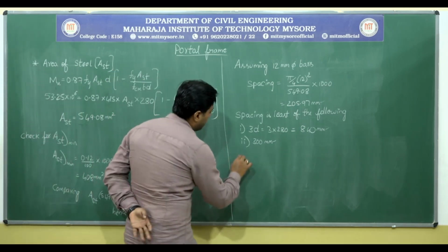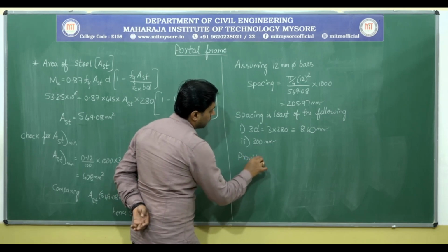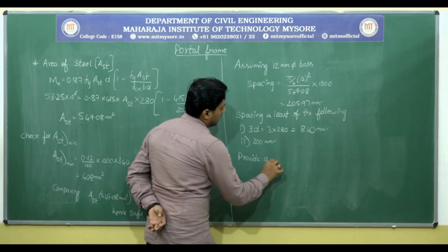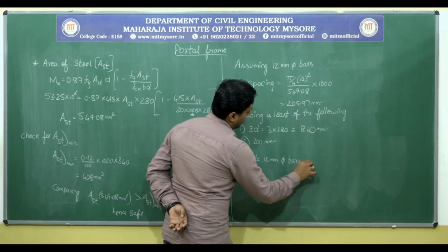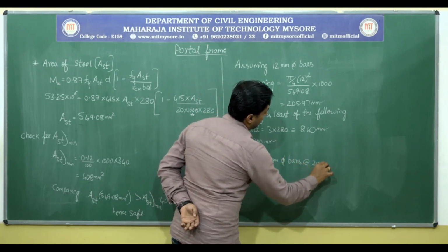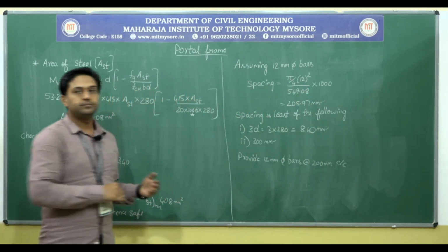So provide 12 mm dia bars at 200 mm center to center.